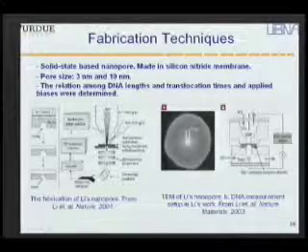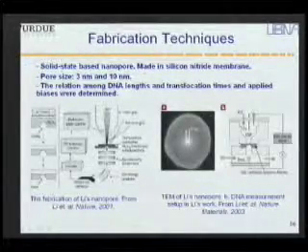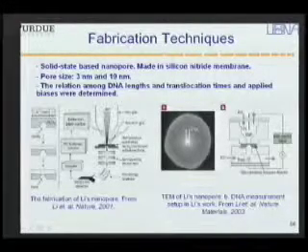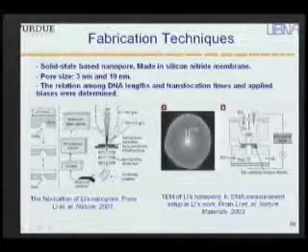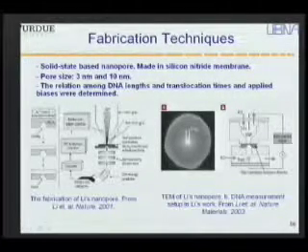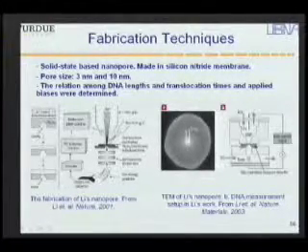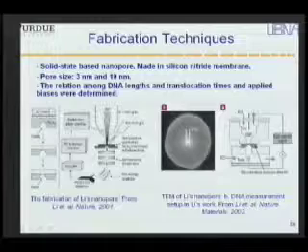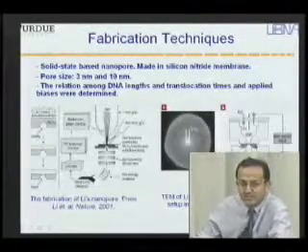And by the way, I should mention that the goal of making these synthetic membranes is very important, because biological membranes might not be very stable under different harsh environmental conditions. If you can find a way to fabricate these sensors using top-down techniques that are more compatible with silicon device fabrication, then you can talk about making arrays of these pores and make sensors that could be handheld, portable, and useful.